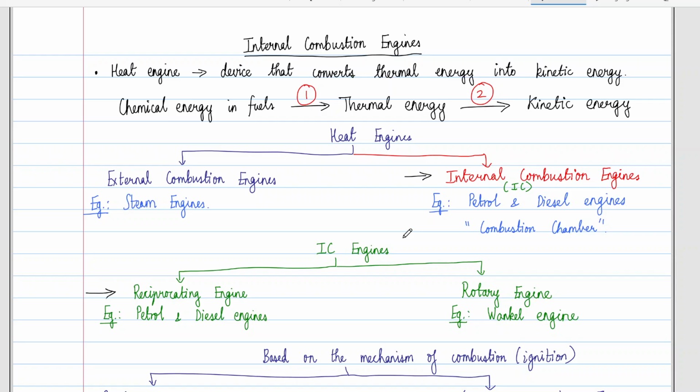The normal force on the tire because of the weight of the vehicle contributes to a rolling resistance force. It originates because the rubber in your tire gets compressed and decompressed, so heating happens and you lose some energy to it. That is lumped as rolling resistance.